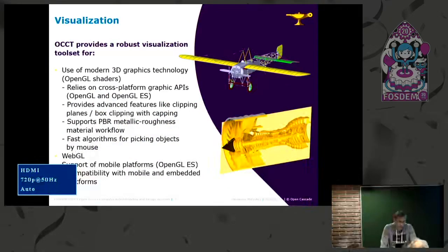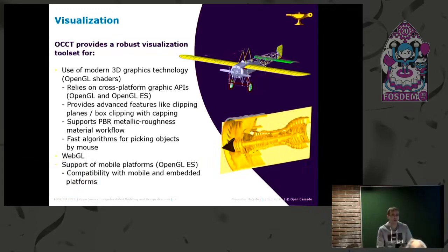Well, visualization is vital for successful modeling. We live in a three-dimensional world, or at least we feel it three-dimensional. Visual feedback gives understanding of what is going on with your parts, assemblies. It is helpful to debug problems of BREP data. Our visualization engine is capable of displaying three-dimensional models, dimensions, relations, and other kinds of engineering data. It uses state-of-the-art accelerating techniques like bounding volume hierarchy to achieve high interactivity and frame rate on huge models.